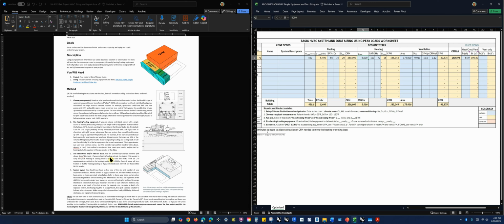You could do heat pump systems to the apartments and then a more centralized system, like we were just talking about, to the lobby and the public areas. If you were doing it that way, then you could just do a full layout for the public areas, which would be pretty simple, not that much more than what you're seeing here in these little sketches. And then maybe do a single apartment, or if you have two different kinds of apartments, one you think is going to need a bigger heat pump and have ducting, and the other, a cheaper apartment, doesn't have ducting, it just has a mini split on the wall. You could do both of those as examples.